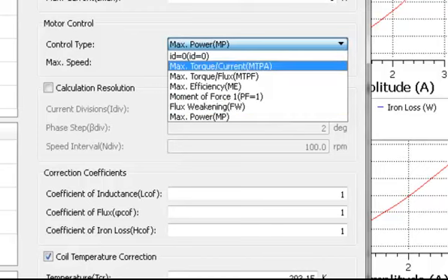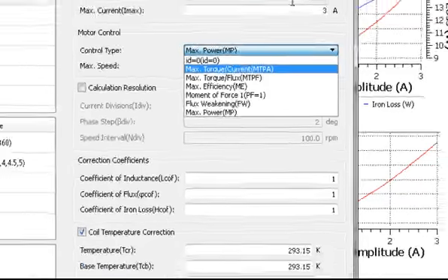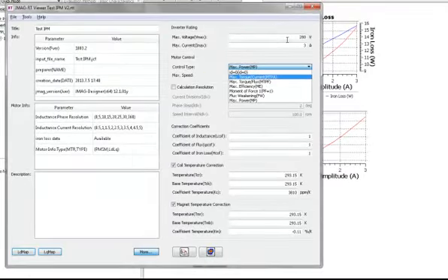So again, with our RT block, the initial level that's coming off of JMAG Express is good to get a basic understanding of machine performance, but we have to move to this higher fidelity model in order to get a truer understanding of machine performance. One of the other features, and before we get back into the presentation, I'll mention that we do have the capability to do the speed torque curve.